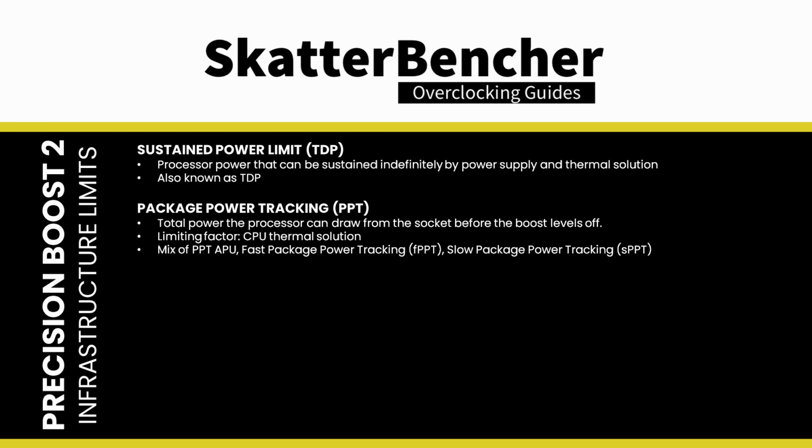In technical documentation, you'll find that PPT is actually a combination of 3 power-related options: PPT APU, fast package power tracking, and slow package power tracking. Depending on your platform, some of these parameters may not be used. For desktop Raphael, fast PPT is the parameter we override when configuring PPT.